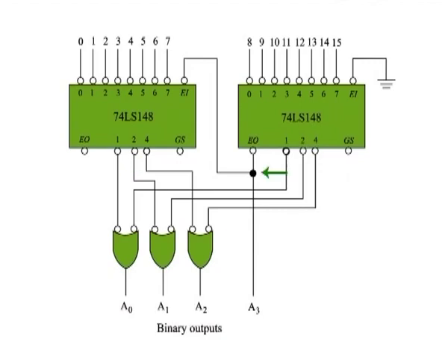The enable output is used as the 4th and most significant bit. This particular configuration produces active high outputs for the 4-bit binary number. An application. A classic application example is a keyboard encoder.